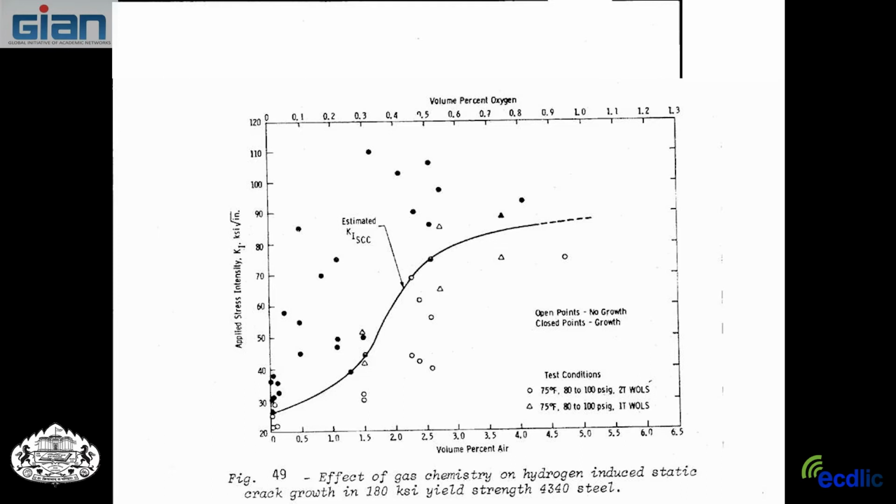So that's corrosion fatigue. Now, the thing I should have pointed out while you saw the pictures is that corrosion fatigue in a bad environment is very particular to the conditions. It depends on the environment, the material, the frequency you test, and it's very difficult to test in one thing and say I'm going to apply that to another condition.